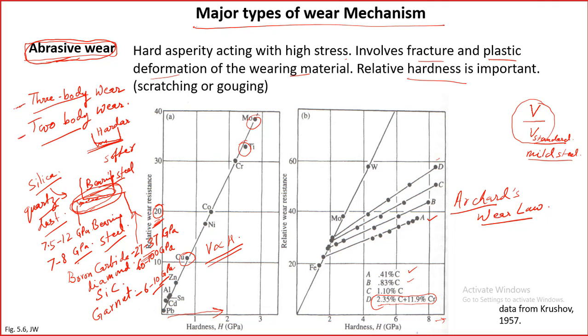If it is 3-body, then your solution approach will be different. For example, all the bearings, for example rolling element bearings, are sealed from any dust particle contamination. They are sealed by a rubber or other kinds of elastomer, so that no dust particle can go in. The IC engines are all sealed from all sides, to protect the wearing surfaces against dust particles. So all tribological systems must have this protection against 3-body wear.